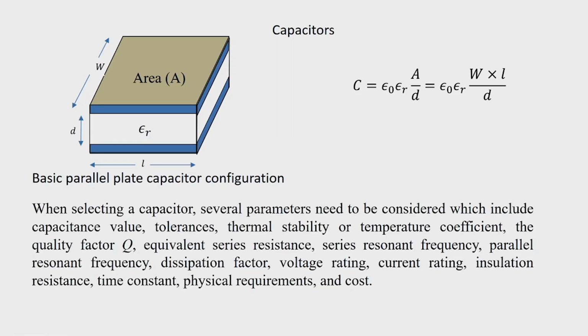When we select a capacitor, several parameters need to be considered, which include, first of all, of course, the value of the capacitor, the capacitance value we need. Then the tolerances, thermal stability and temperature coefficient. The quality factor: a capacitor is to store charge, and quality factor will determine how much energy is stored and how much power is dissipated.